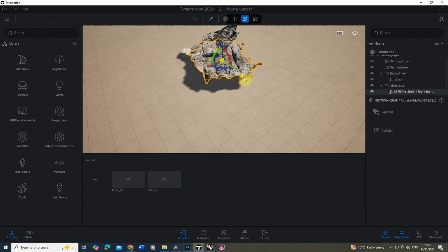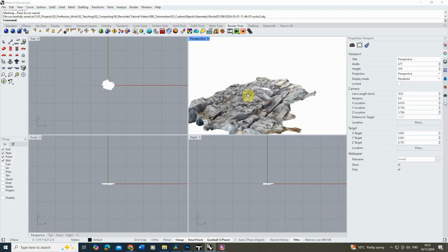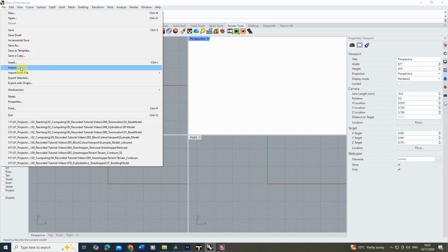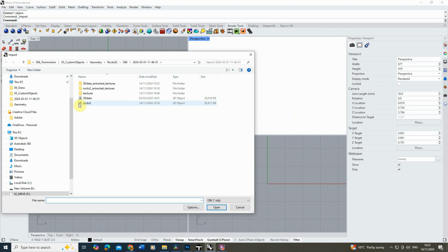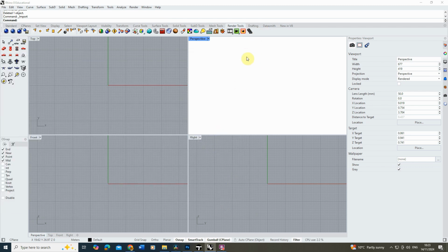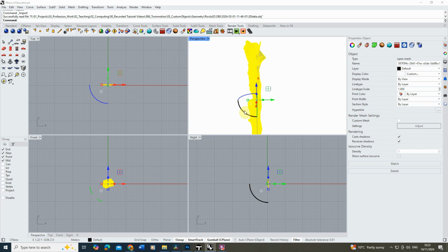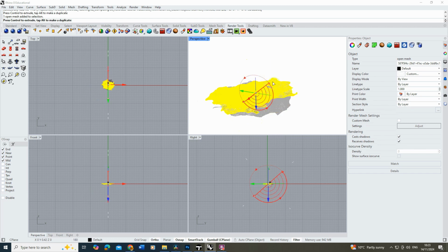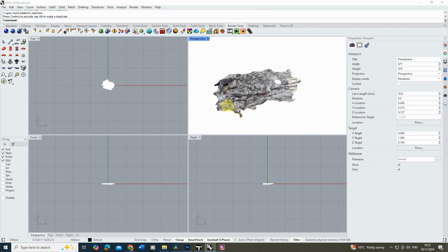a software like Rhino. So usually what I'll do is I'll quickly open up Rhino, and you can see I brought this in previously, and we'll do it again here. I'm just going to click Import, find that 3D data, open it in, select OK there. Then I'm just going to rotate that around in my Rhino file, make sure it's the right way up, and just holding down the Shift key to lock that in.